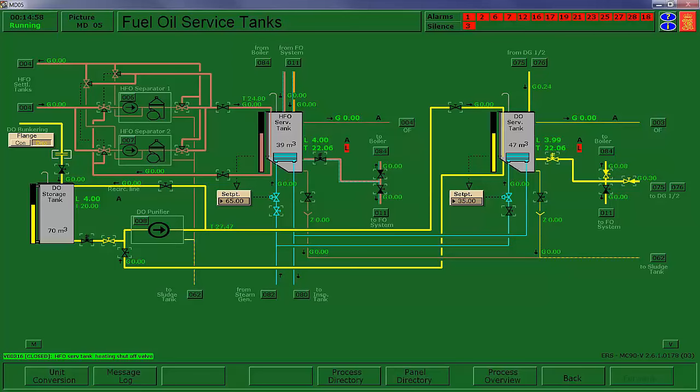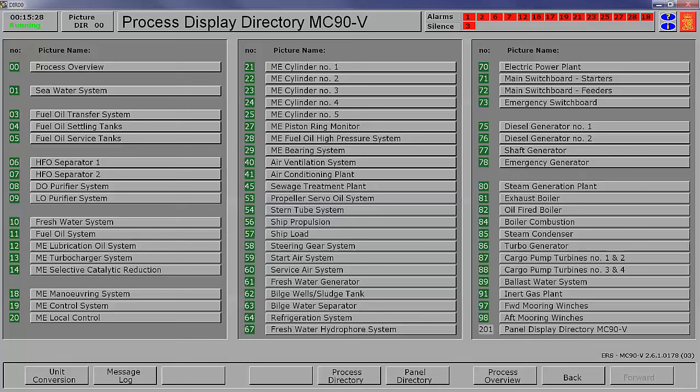And we'll put the steam on both the heavy and the diesel. Again, the set point here is 65, though I see people running this up to about 80. And again, think on how much vapor you're producing. They do it because some of the modern fuels put a lot of load on your fuel oil heaters for the main fuel system. All right, so we've got that. Now the next thing we're going to do is go to that refrigeration system, and it's fairly simple to put on.